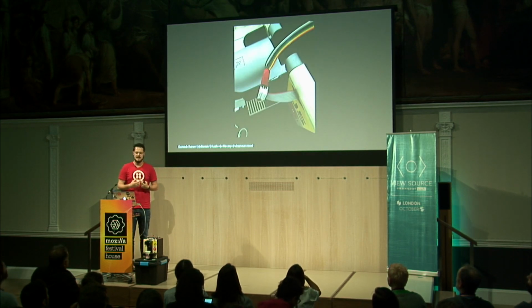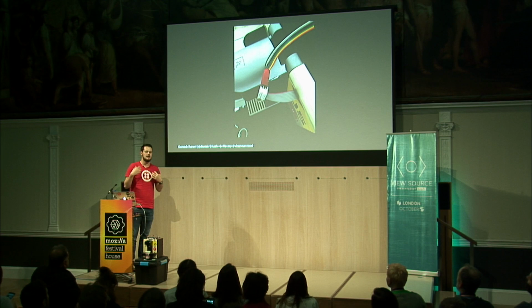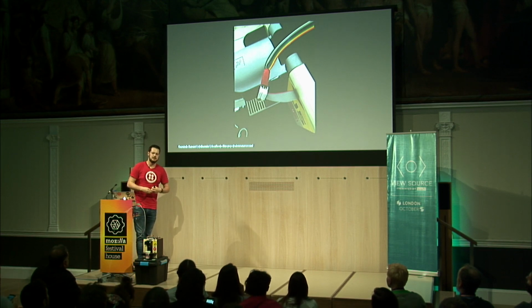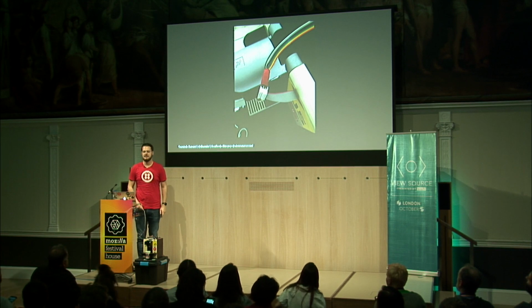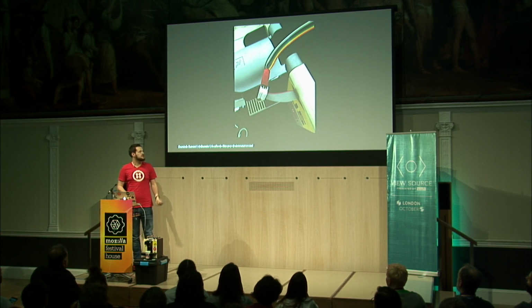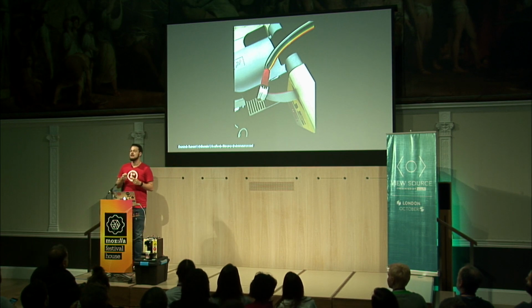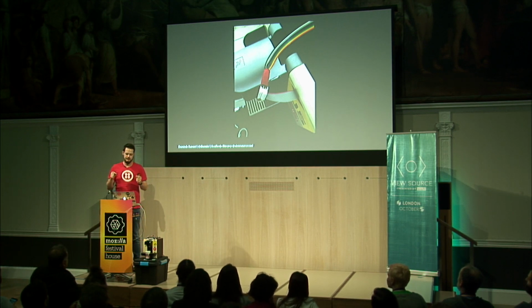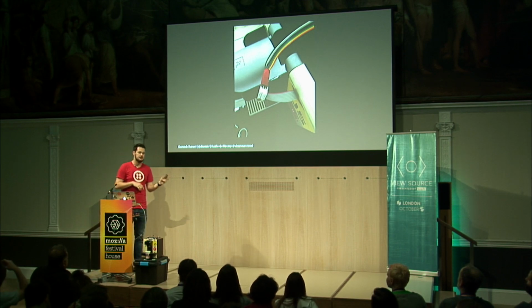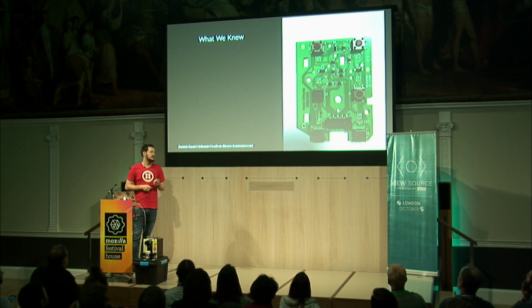And then our idea was that if we would reverse engineer the protocol that is transferred via this cable, we can sort of spoof the control plate and instead use our Tessel to send in the commands. So in order to reverse engineer the protocol, we just jammed a bunch of jumper wires into that cable. It sort of fits up to today, so sort of works. And then we connected one side to the control plate and the other side to the Tessel to figure out what's the protocol there. So what did we know just by looking at the board?